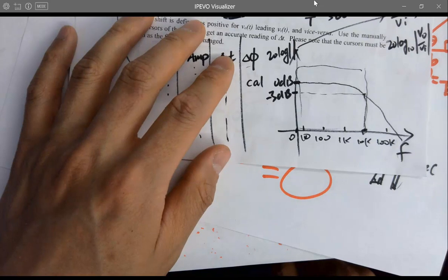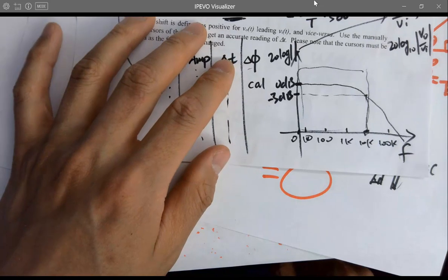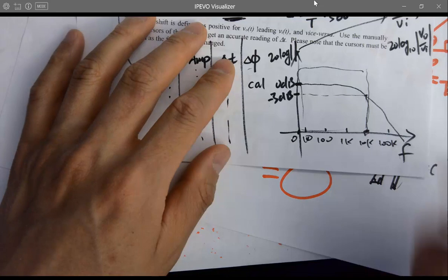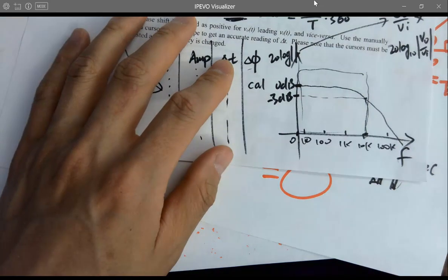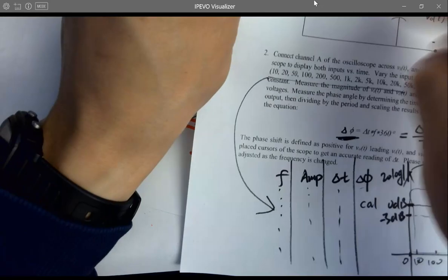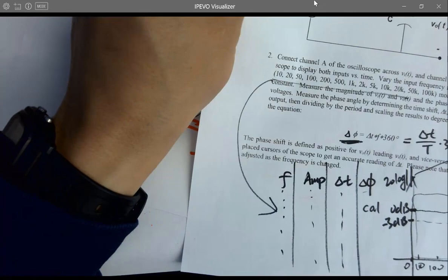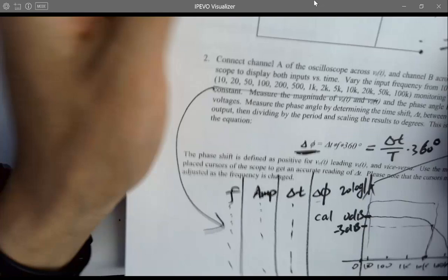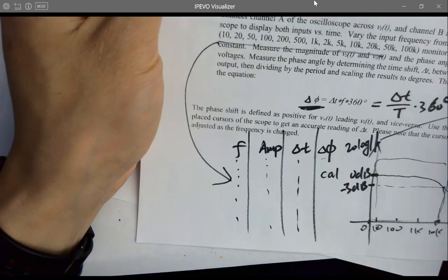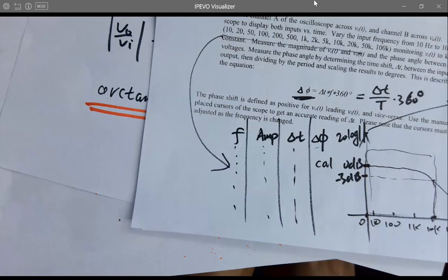Any questions so far? Deeper slope, you mean steeper? Yeah, higher order of filters. So adding more caps and resistors in here. Or use the active filter, adding op amps in there will help as well. There are a lot of things about filter design.